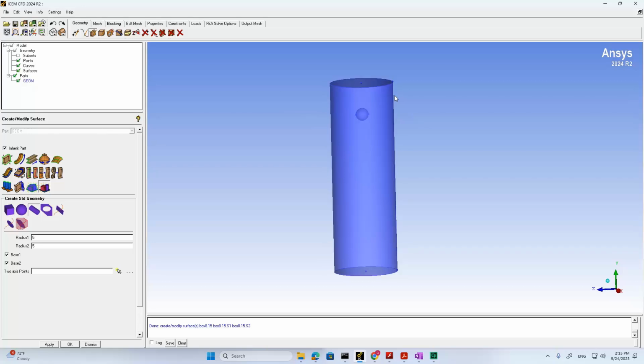And the second thing you have to give Fluent is a mesh. So remember this. Whenever or wherever you want to solve partial differential equations and to get useful information, like velocity, pressure, you have to provide a mesh there. So basically you will need a mesh everywhere in your computational domain. That's the second thing you have to provide.